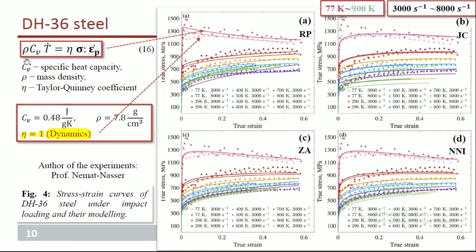However, using the same equation 16, other models only provide a weak tendency towards this softening behavior, whereas the RP model can quantitatively capture this non-monotonic behavior. One of the reasons is the introduced temperature-time correspondence, because during deformation the temperature rise further reduces the relaxation time value. That leads to a more pronounced stress relaxation, which means the softening behavior.